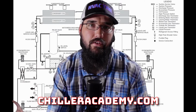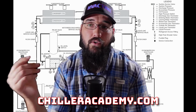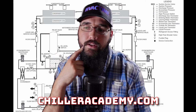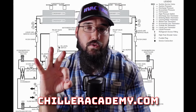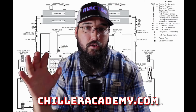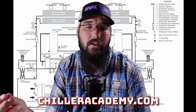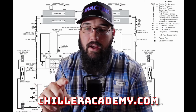So having a system that not only is variable speed, has a slide valve, and has the ability to have hot gas bypass, all three in the same system, they do it successfully. At least they have so far. I've worked on Dunham-Bush units specifically that do that, but it just makes you ask questions, right? So anyway, that's the third style that you'll see with screws from a loading standpoint, or load control for staging: slide and variable speed. They'll use them simultaneously, or either way, you get the point. So from a limits perspective, let's cover that to wrap this up.